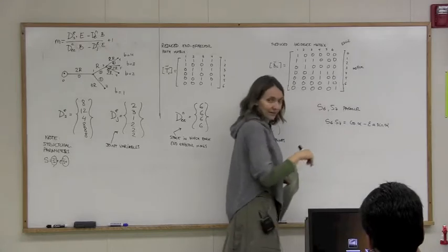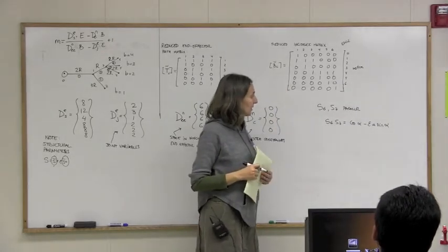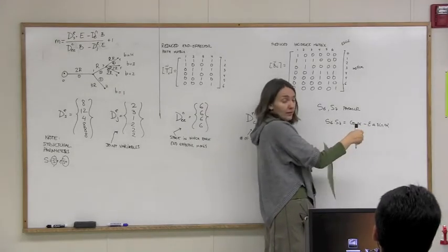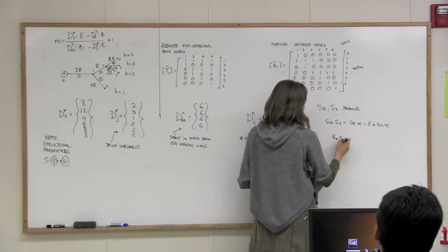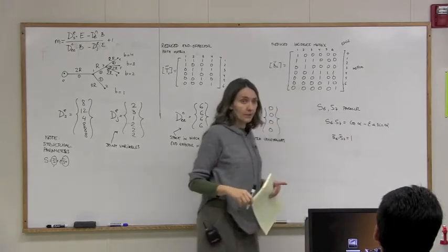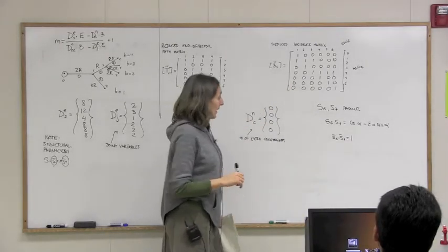Remember the dual geometry, when you do the dot product of 2 lines, you get that. So if what you want is this angle to be 0, right? So cosine of alpha equal 1. So you would say S6 dot S7, the direction vectors, equal 1. Okay, that means they are parallel. Alpha equals 0.